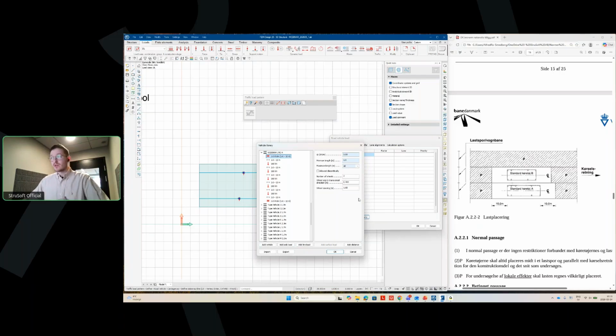And how we deal with that in 3D Bridge is that we get to set a maximum distance that can be all the way up to infinitely long. And this is what we will select here. For the minimum length, I guess 1 meter is fine. We can keep it. Here we also have the option to allow a discontinuity, which means that the software will allow for gaps within the distributed load. Right now we can keep this unchecked, I think.